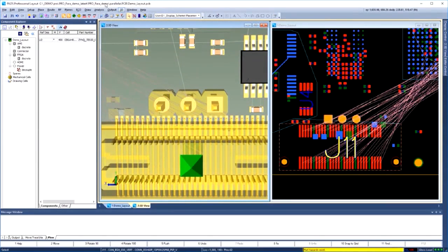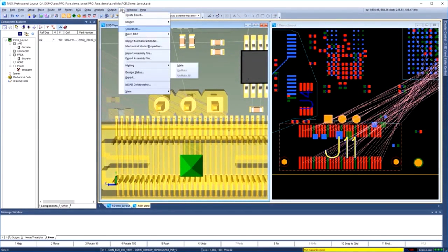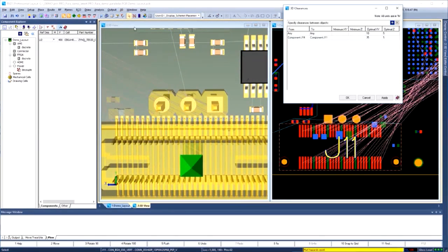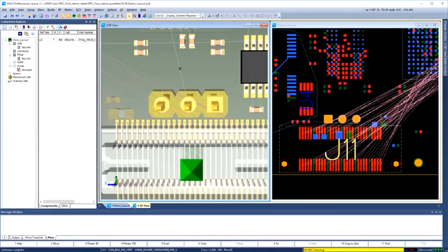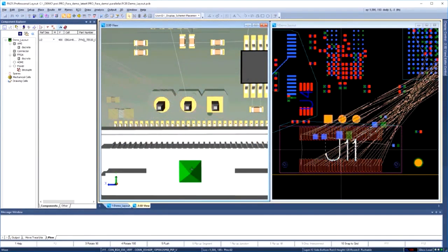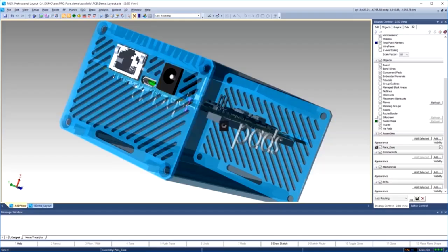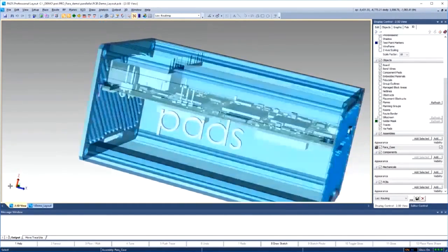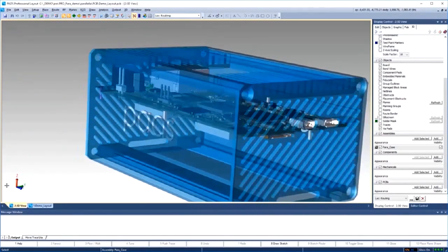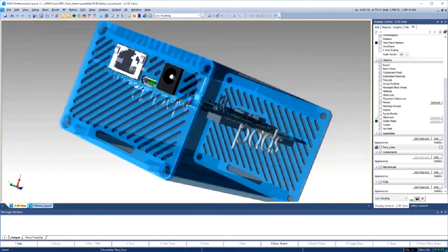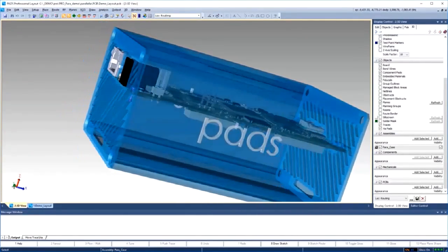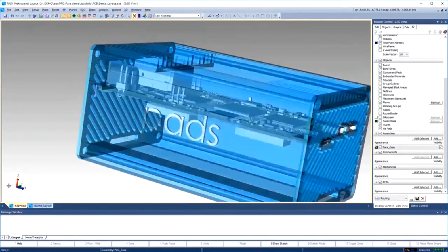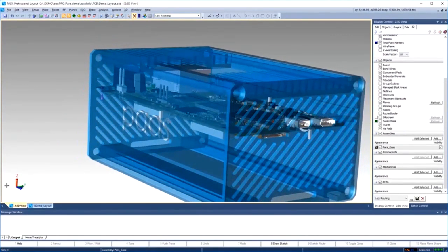To ensure proper clearances between components, set up global and custom clearances between specific objects and components. Perhaps a connector needs extra space on one side during insertion that is not represented in the mechanical drawing. By viewing the design in 3D, one can visualize how the PCB could be assembled or interfaced with. You are also running DRC verification checks before the system is ever physically created or sent out for prototyping, potentially reducing time to market by left shifting electromechanical issues earlier in the design cycle.